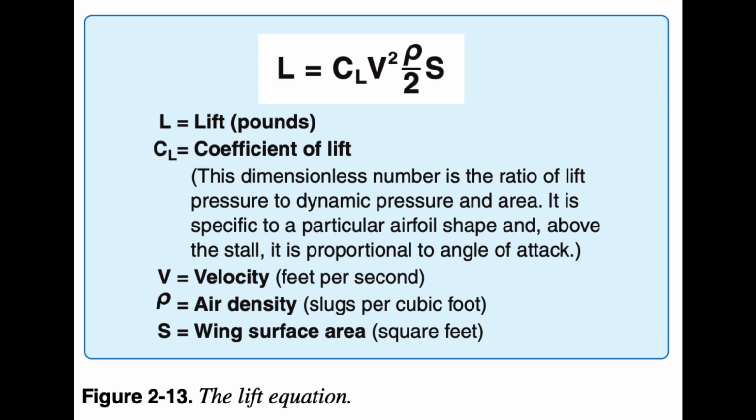Because lift is a function of dynamic pressure, Q, it is proportional to the square of the airspeed, therefore, small changes in airspeed create larger changes in lift. Likewise, if other factors remain the same while the CL increases, lift also increases. The CL goes up as the AOA is increased. As air density increases, lift increases. However, a pilot is usually more concerned with how lift is diminished by reductions in air density on a hot day, or if operating at higher altitudes.